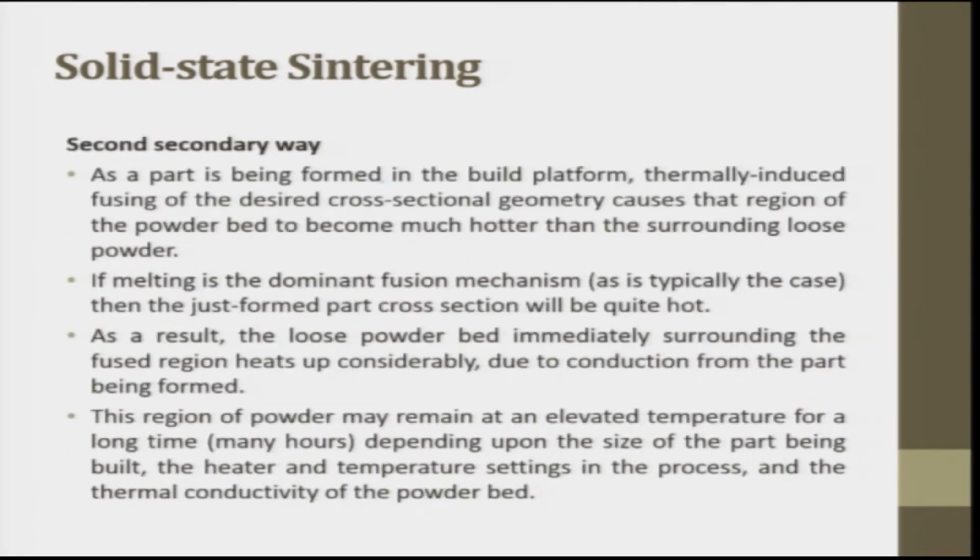As the part is being formed on the build platform, thermally induced fusion of the desired cross-section geometry causes that region of the powder bed to become much hotter than the surrounding loose powder at the cross section, right. If melting is the dominant fusion mechanism, then the just-formed part cross section will be quite hot when you are doing selective laser melting.